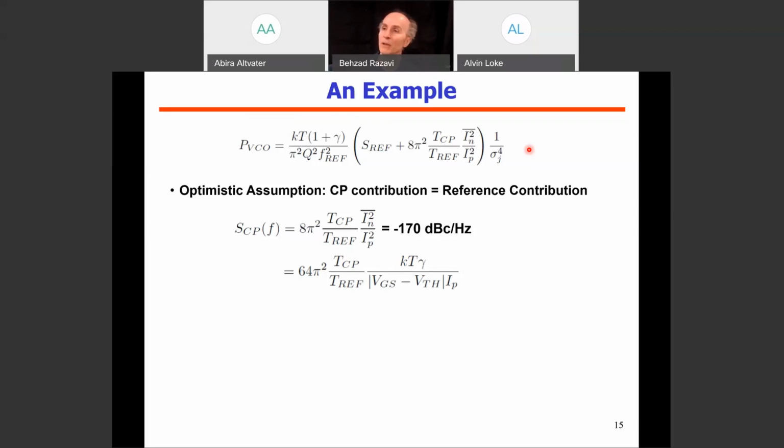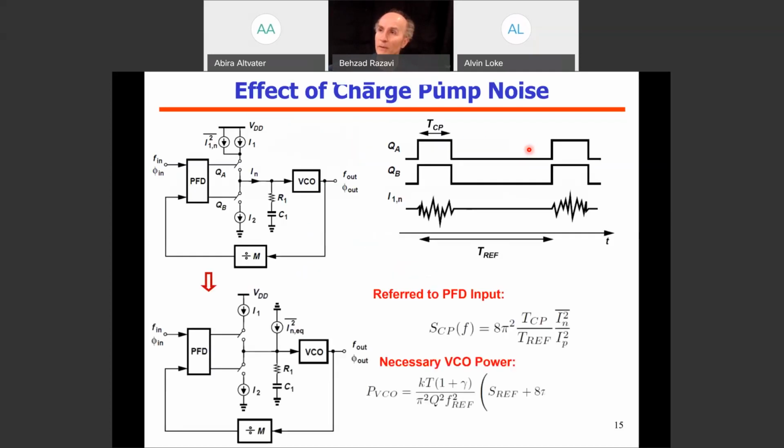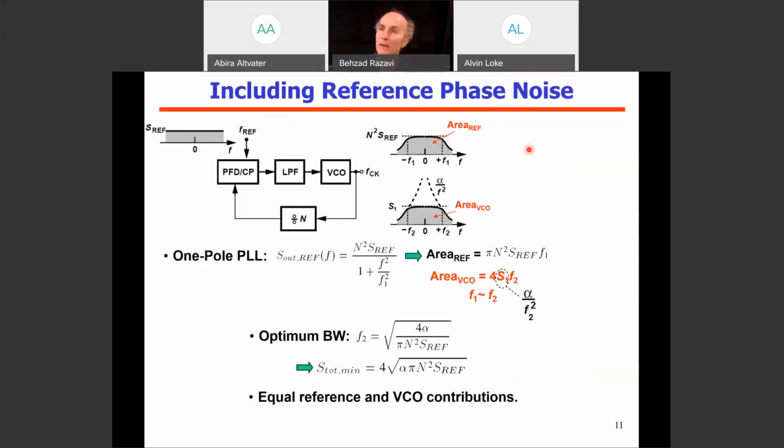Yes, very good question. Okay, so again, the situation will be worse. If we go back to some of these profiles that I used as an example, we will have some phase flicker noise from the VCO. There have been some recent examples. I think there was a class F oscillator reported a few years ago that does have a very low corner frequency for its flicker noise, down in the range of tens of kilohertz. That's very impressive, and certainly it would be a good candidate for what we're doing here.